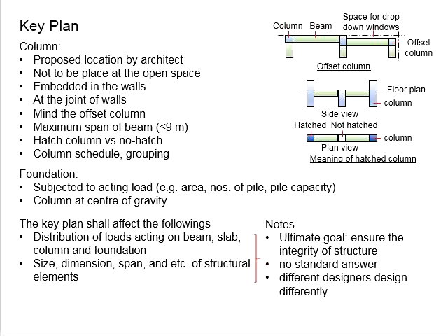Unless the building is much taller, where the loadings are extremely high, if you use RC piles, the number of piles becomes unrealistically large. This is when you are going to need these spun piles. Of course, there are also other considerations, because depending on the pile conditions, it can be end-bearing or frictional piles.